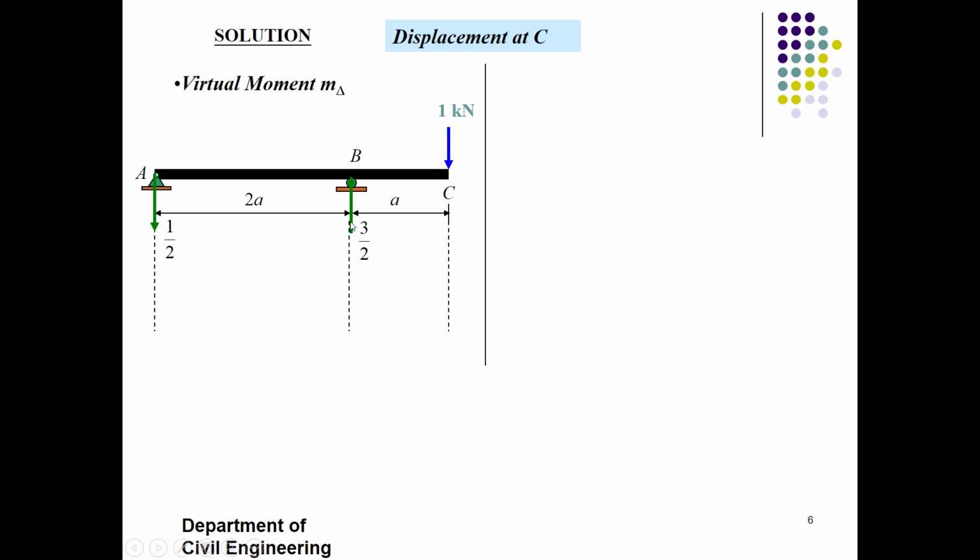You can solve sigma Fy equals 0, sigma moment equals 0, or transform this value into some moment value and then take your values. So after the calculation of reactions, you will draw the moment diagram, as we are interested in the deflection. For the moment diagram, you can draw the shear diagram as well to calculate the moment diagram easily, or cross check your moment diagram. In this case, the moment diagram is minus a over here and then goes up to 0 at the free end. So the value of moment at this support is negative a.